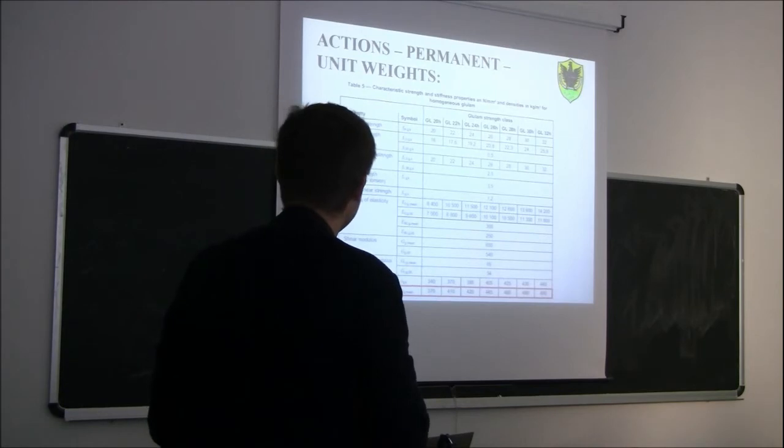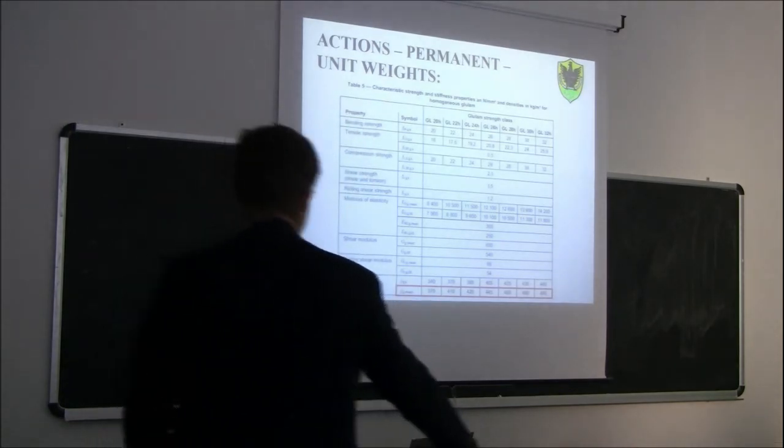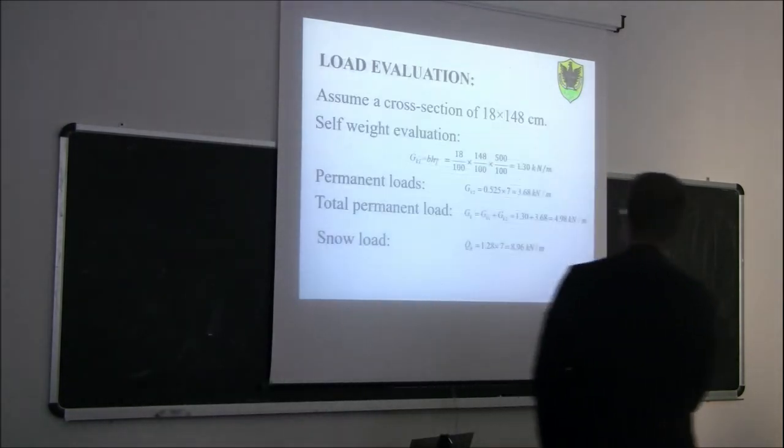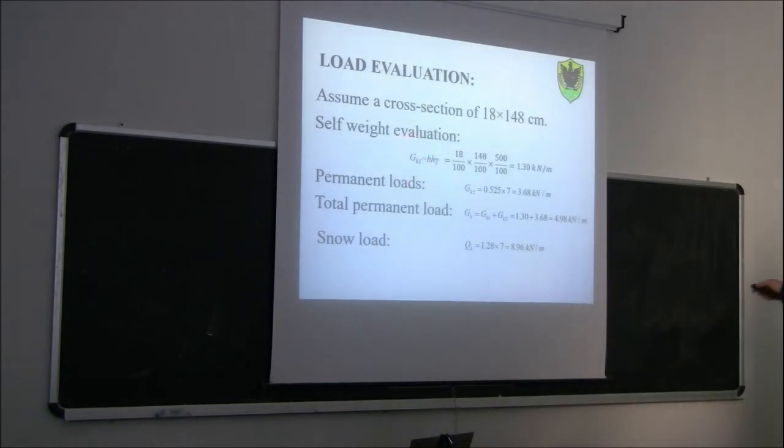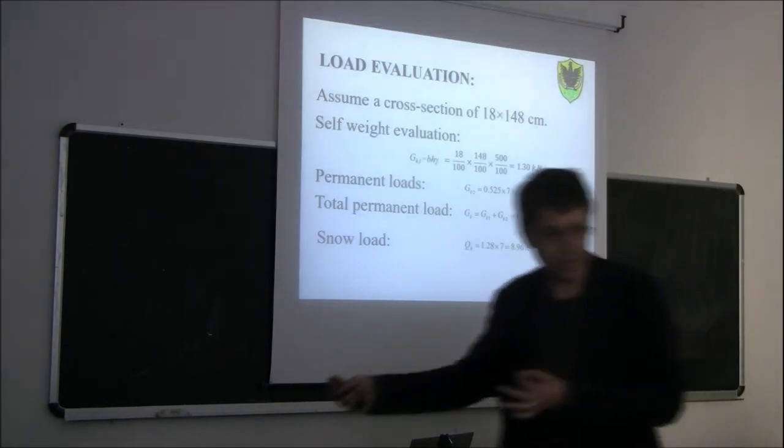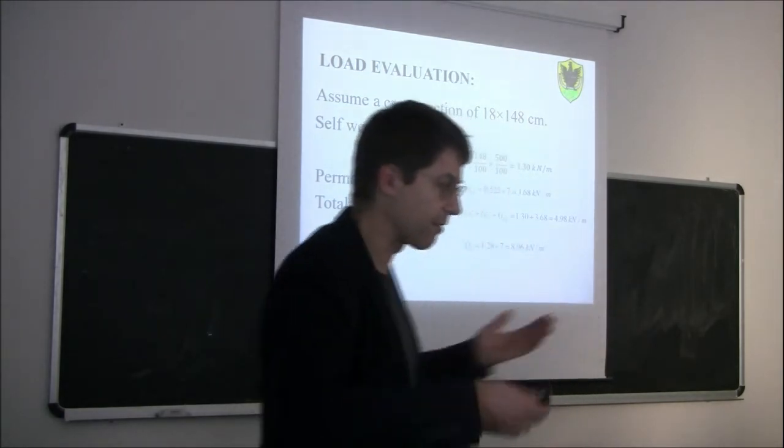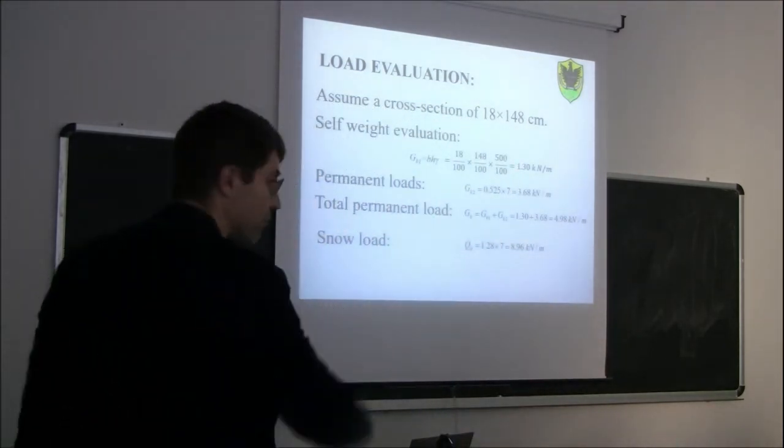Good, so going back, what we did, we calculated the self weight of a beam. Like I told you during the structural design course, when designing a beam we need to find out the uniformly distributed load, which is expressed as a force per unit length. So the unit of measure is kilonewton per meter.